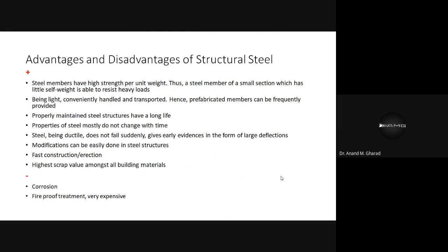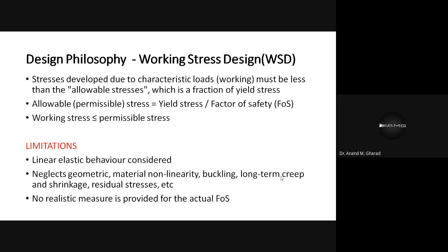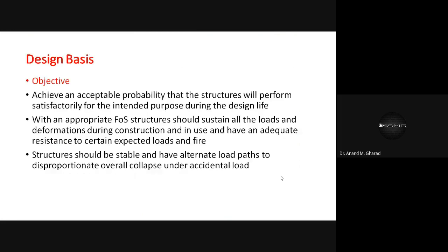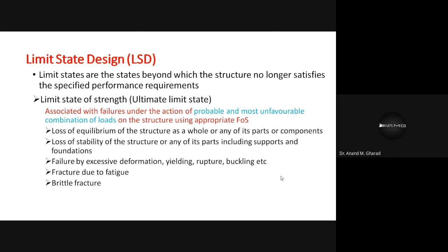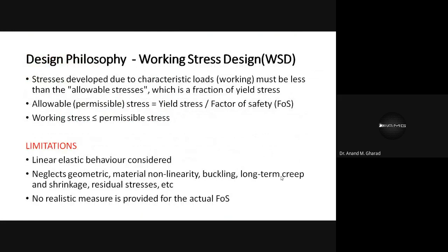And in the practical slot, I had also discussed the physical properties and the design philosophies like the working stress method and the limit state design method. Working stress method, as you all know, depends only on the elastic behavior of the material. It has very few advantages, but lots of limitations or disadvantages, like it neglects the geometric and material nonlinearity, buckling phenomenon, long-term creep and shrinkage, residual stresses, etc.